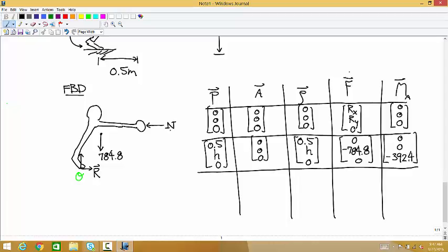And now this force N, that roller force, we know the vertical coordinate. What's that? 0.8. But we don't have a horizontal position. There's nothing given that tells us how far away horizontally the wall is. So I'm just going to call that W. So we have W, 0.8, 0. The about point is the origin.